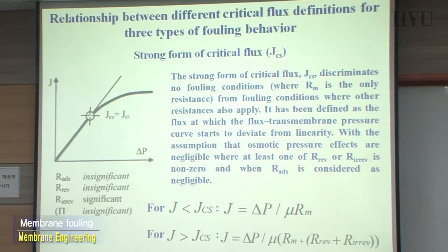Now, normally in this kind of relationship, we are assuming that the adsorption is not significant, the reversible fouling is not very important, the osmotic phenomena are not significant, but the irreversible, when you start to have a deviation, is significant.